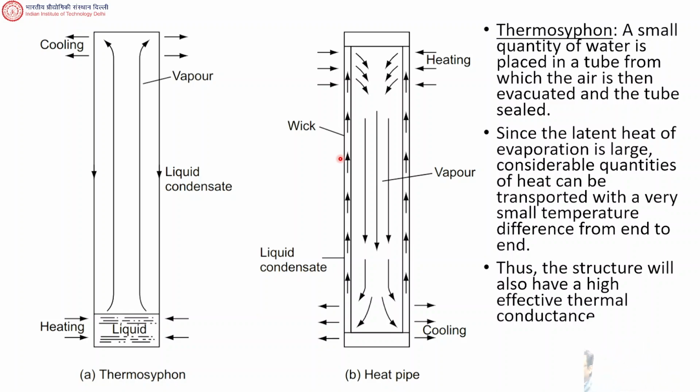Okay. Now this is something which gravity is obviously not doing, right? In this case, the condensate came down because of gravity, but here in the heat pipe, the wick is doing something. Something is happening, so the liquid is actually going up, right? So effectively, what you are doing is you are transferring heat and taking it out from here. So this is transporting heat. This device, which you are calling heat pipe, is transporting heat.